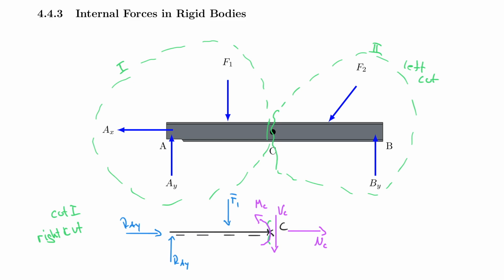And I say it again, the trick that engineers use is we pretend that this is not there initially, and ask what is the imbalance that I have to balance or bring back into equilibrium by using these purple forces here. And hopefully you are looking at this right now and you say, this is actually an easy problem for me now because I can already calculate these forces. This looks exactly like what I've done when I solved cantilever problems.